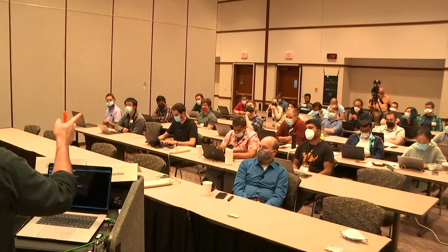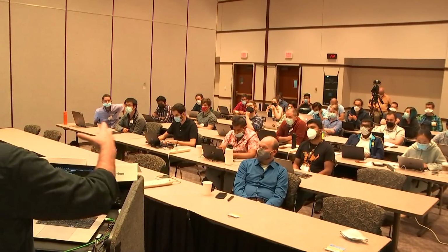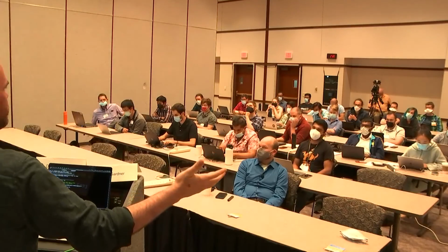Yes. Well, I think you guys are both right in that this is going to essentially start diffusing towards some sort of pretty much steady state. The problem is going to diffuse out and become more homogeneous, and it's going to essentially get easier and easier as time goes on. And the integrator's tracking that. Seeing the problem's getting easier, I can keep pushing the time step size up and up and up, and it keeps doing that throughout the rest of the problem.